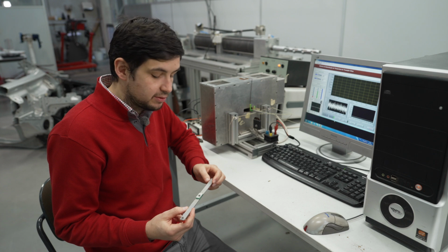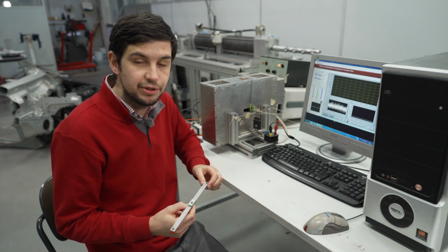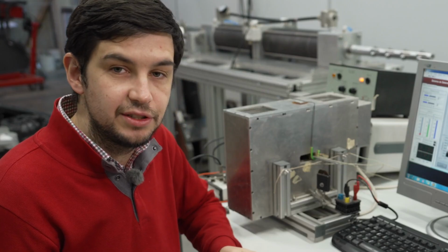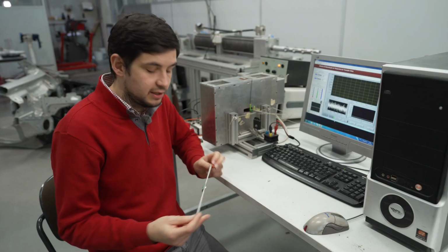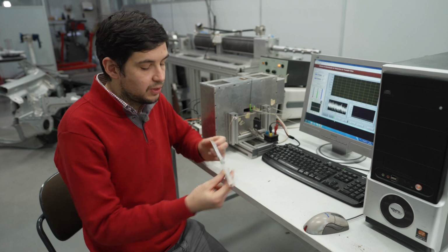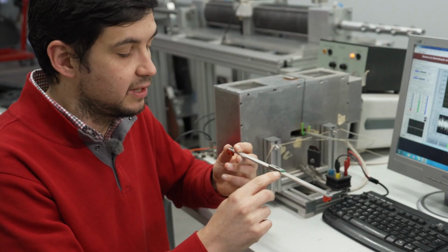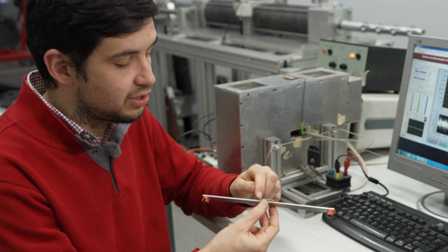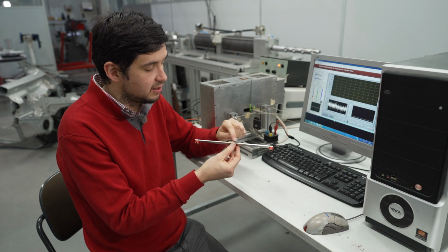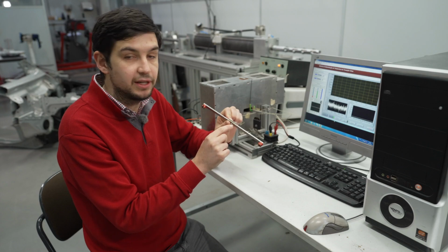I'm going to talk about this machine that we have that is called glass transition temperature measurement device. This machine is used to determine the glass transition temperature of polymers, such as the adhesives that you see here. So how does this machine work? We have this specimen, which is a beam, and this beam has adhesive inside this constrained layer that you can see here. So there is a metal sheet. The adhesive is located here between the layer and the beam, and it's fixed in position by a screw.